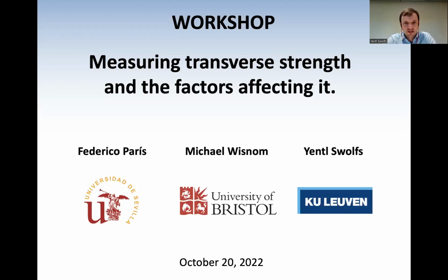The goal is to set up best practices to determine which specimen designs work best, which grips work best, and how these materials should be cut to get the most reliable measure for longitudinal tensile strength. The longer-term goal is a specific ISO standard for UD composites, in addition to the more generic ISO standard that already exists.